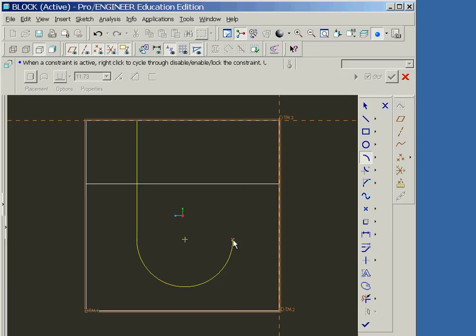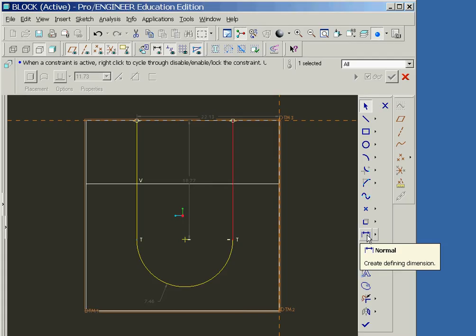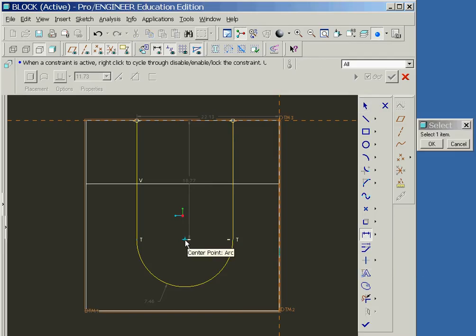Next, we'll use the right mouse button and select the Line option and define the line shown here. Now we'll click the middle mouse button twice in order to return us to Select mode. We need a dimension from the middle of the arc to the right edge of our sketch, so we'll click on the Dimension icon, and then left-click on the vertex at the center of the arc and the reference line, followed by clicking the middle mouse button where we want the dimension to appear.